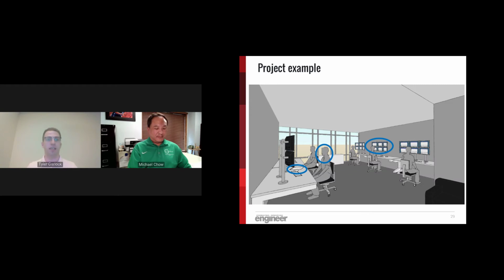And then given the fact that it's a 24/7 facility, you have to think about controls, because the general principle for lighting with daylight is that you want brighter days and darker nights. So you might want a little bit brighter during the morning, so you'll have the lights up higher, and a little bit dimmer at night as the sun goes down, to give that visual cue for the people working in these spaces for long periods of time.